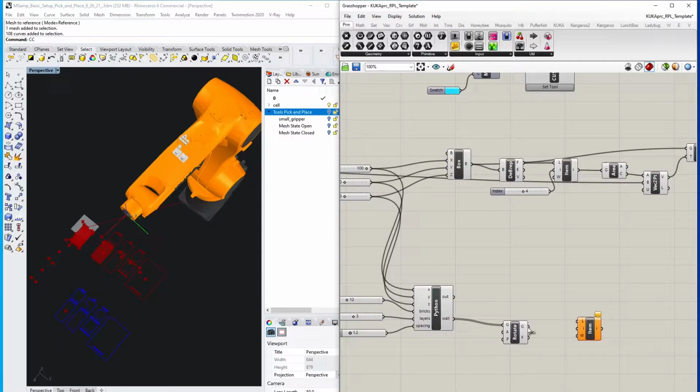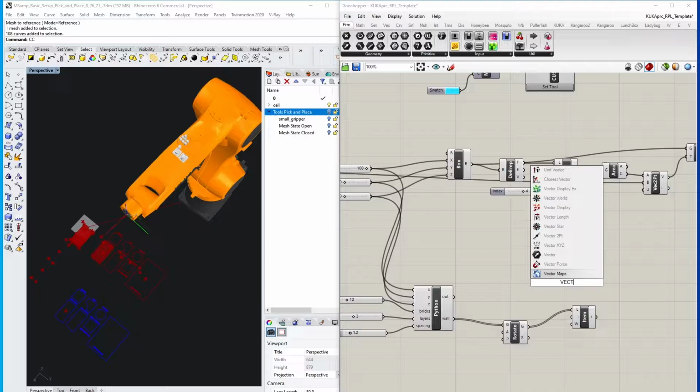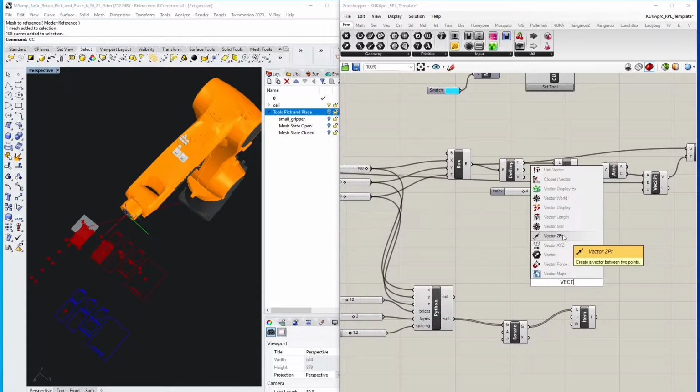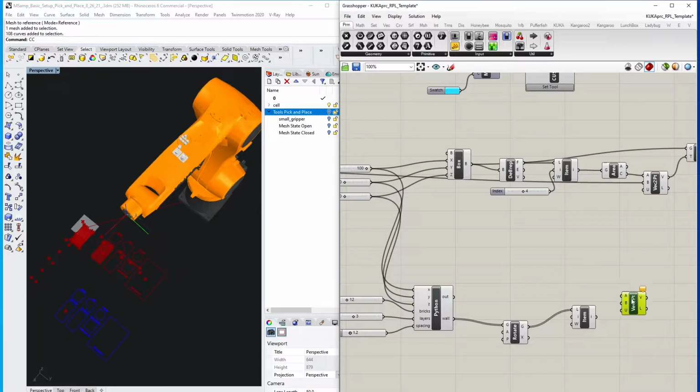The point we actually wanted to map to is the first point, the starting point for our brick wall. So we don't need to actually indicate what index we want, but we do need to do another vector 2 point command to move our geometry.